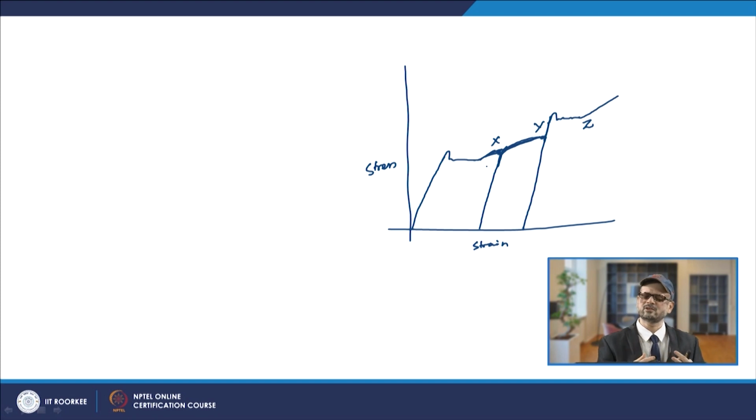Now the effect of strain aging is that it increases the yield point, and it also leads to a decrease in ductility and a low value of strain rate sensitivity. Also, because of the strain aging, you will have serrations in the stress strain curve. This is known as the dynamic strain aging behavior.